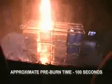The objective was to have total product submergence in less than 2 minutes. Because of the dangers of running fuel fires, this is actually 1 minute lower than the standard requires. The flammable materials were ignited and allowed to pre-burn for approximately 100 seconds before the system was actuated. This is well beyond the normal reaction time a typical UVIR fire detection system would normally take to detect the fire and actuate the foam system.